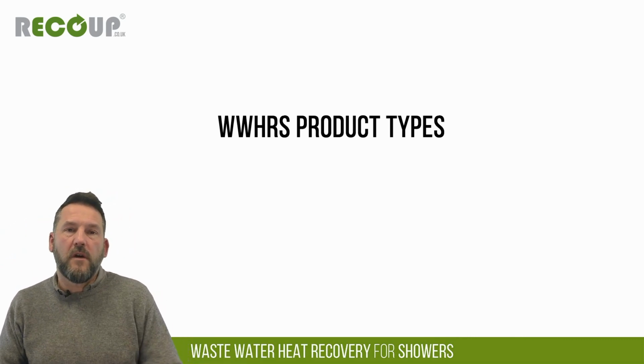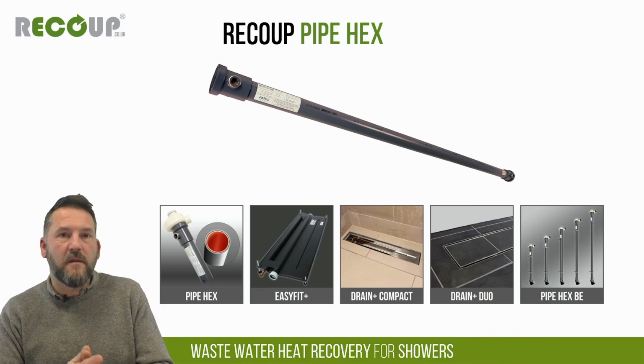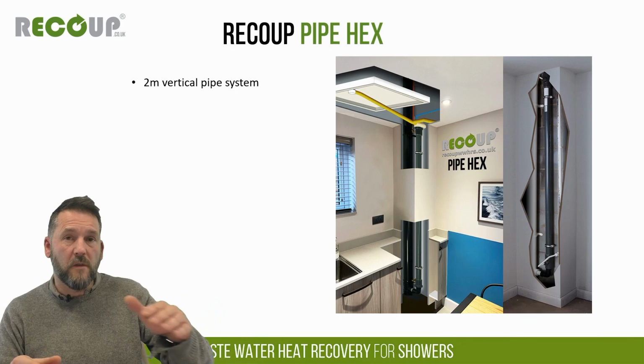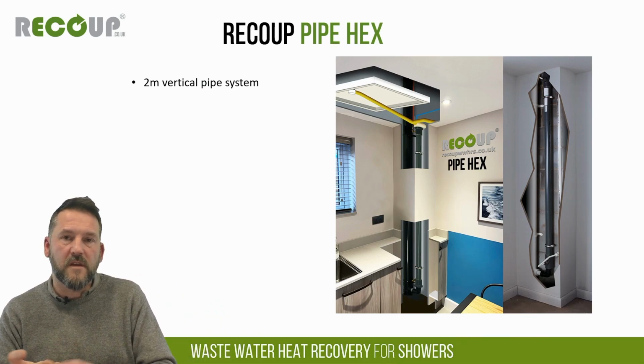So just going to focus on the wastewater heat recovery products themselves. So as I said, the main product that's specified, and certainly the most specified product for new build housing is the pipe hex. This is a 2 metre, in fact a 2.1 metre vertical heat exchanger pipe. And as you can see, it's normally boxed in next to the SVP on the ground floor below the shower it connects to. Would normally install ideally within about 3 meters of the shower waste pipe. In practice, because of falls on waste pipes and things, it's quite difficult to be further away than that. So 3 meters is usual.